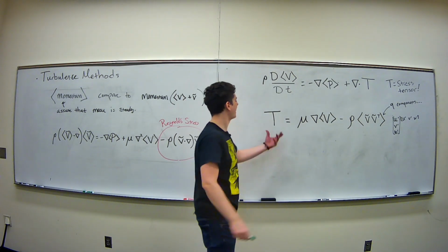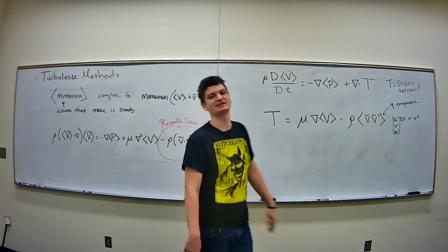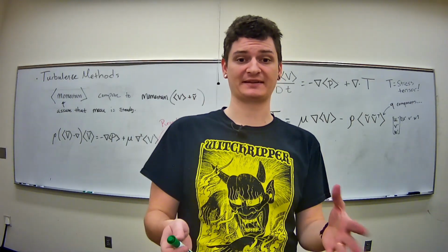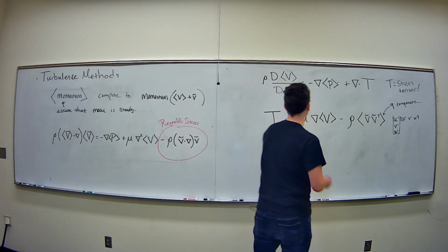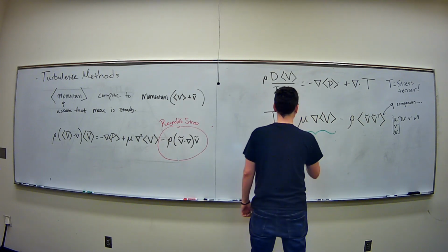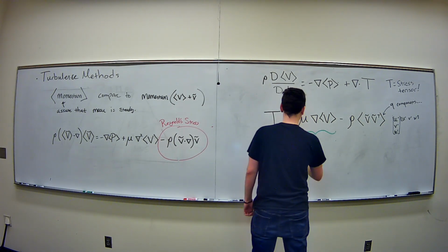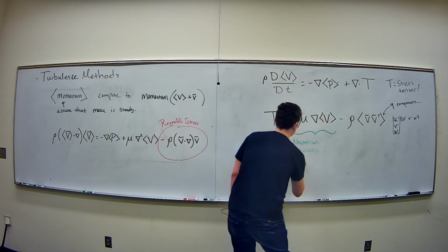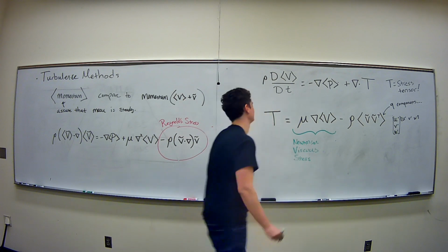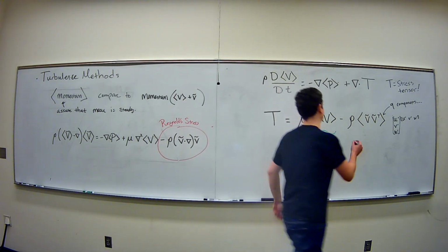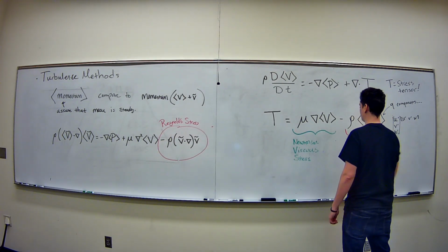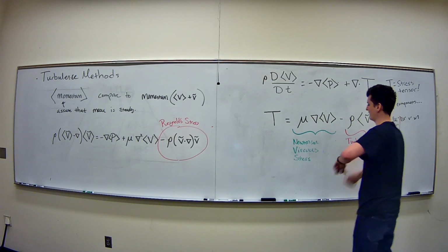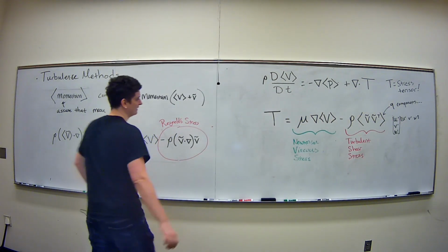So everything now in the turbulent case of flow, with my assumption that the solution looks like this, don't really know if it does, experimentally it really does though, right? You get the extra term, which is the Reynolds stress, right? So then what do you have? You have this is Newtonian viscous stress. Okay, Newtonian viscous stress. And then here is this extra term now, where this is going to be a turbulent shear stress. I would really say Newtonian viscous shear stress, turbulent shear stress, right?